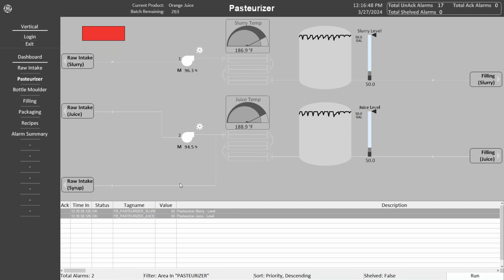So we have a couple different ways we can bolt on to this system for reporting and analysis. We can look at a history of the alarms, right? How many are happening over time, what areas they're happening the most in. We can look at the live data, for the purpose of triggering information, or we can tell when a process is starting or stopping for the purpose of capturing data. And we can look at all that high resolution tag history as well in terms of, throughout that process, what was the trend on the level or the temperature, the min, max, and average of these variables.